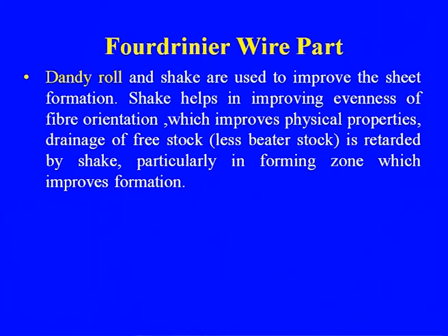Shake helps in improving the evenness of the fiber, because the fiber has to be distributed on the wire part, which improves the physical property. Drainage of the free stock is retarded by shake, particularly in the forming zone, which improves the formation, because we cannot afford to lose the fiber also. So, that is also very important.